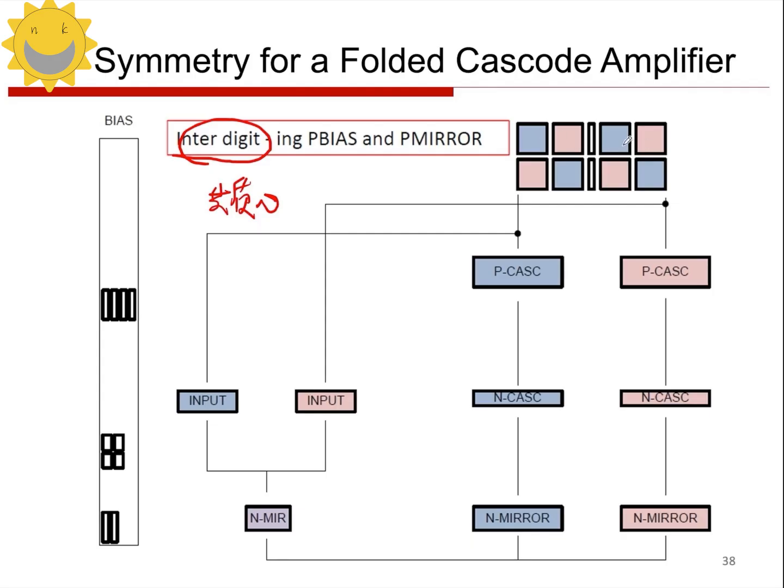ABAB, then BABA is a layout for the finger center, right? After the arrangement, we add the bias circuit to the middle. In this way, first, these two devices are arranged symmetrically around the bias circuit as the axis, creating a coaxial symmetric structure. Then, each part is arranged in a cross pattern for the common centroid layout. So this part completes a layout.